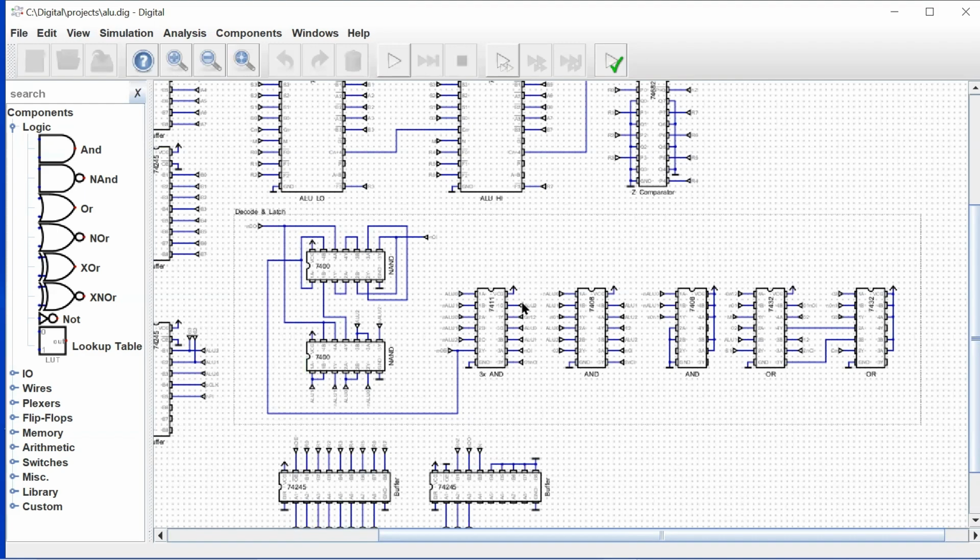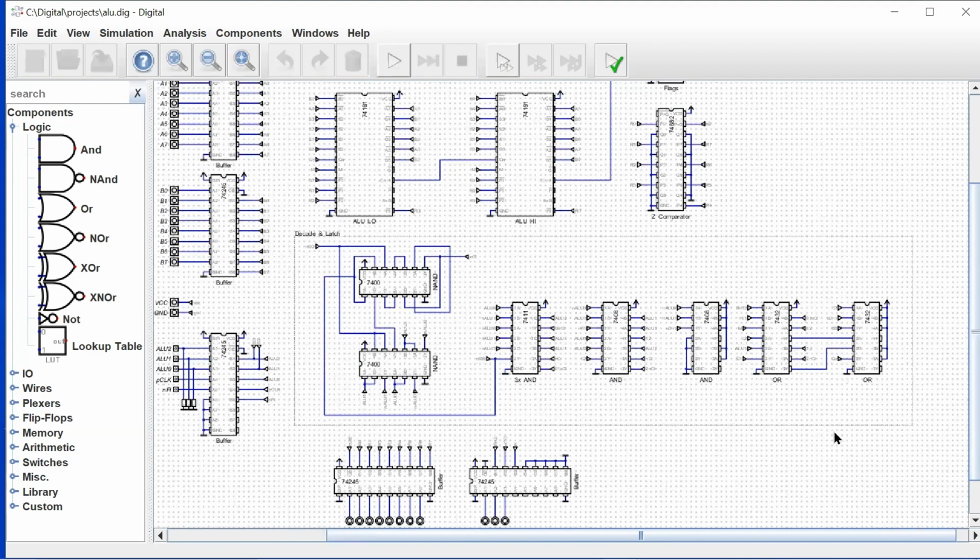Those types of chips are kind of out of date, but anyway, I'm going to do my best to replace this whole decode logic with one chip if I can. It may only be these chips that I can simplify into a single chip, but in any event, I have the potential to eliminate 4 chips here, or maybe all of these, with one single programmable array chip. But we'll see how that goes.